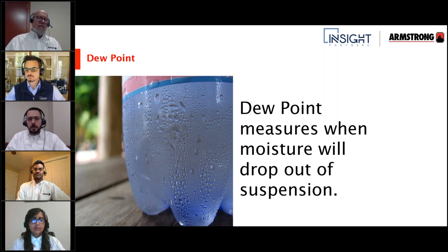If I need that 40-degree dew point, or I need a 35-degree dew point, let's say it's a hospital operating room or some industrial process that needs that really nice dry air, if my chilled water temperature is too warm, I can't do any dehumidification. So I have to know what the dew point is that is required to get to where I want to be, and that in turn drives my chilled water supply temperature. Because if I don't have the two right, the system won't work.